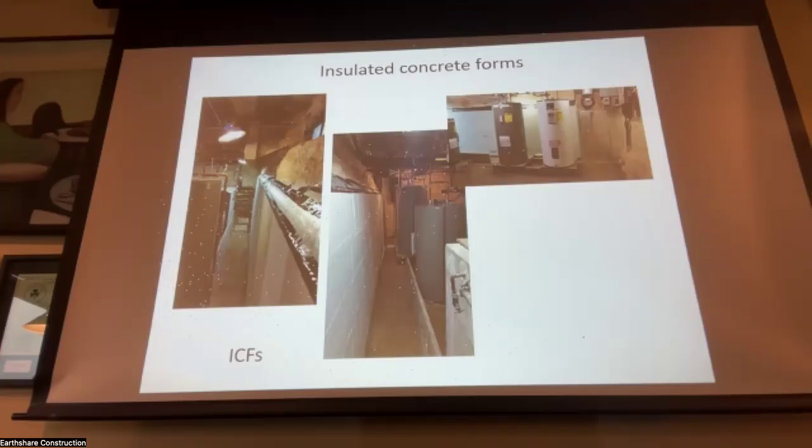Is there any scenario where you want to leave some of that rubble foundation exposed and terminate your 15 mil poly above your high water? If it's a chimney or fireplace space, definitely. Or columns coming up. It depends on whether you're trying to dry or protect from wet.